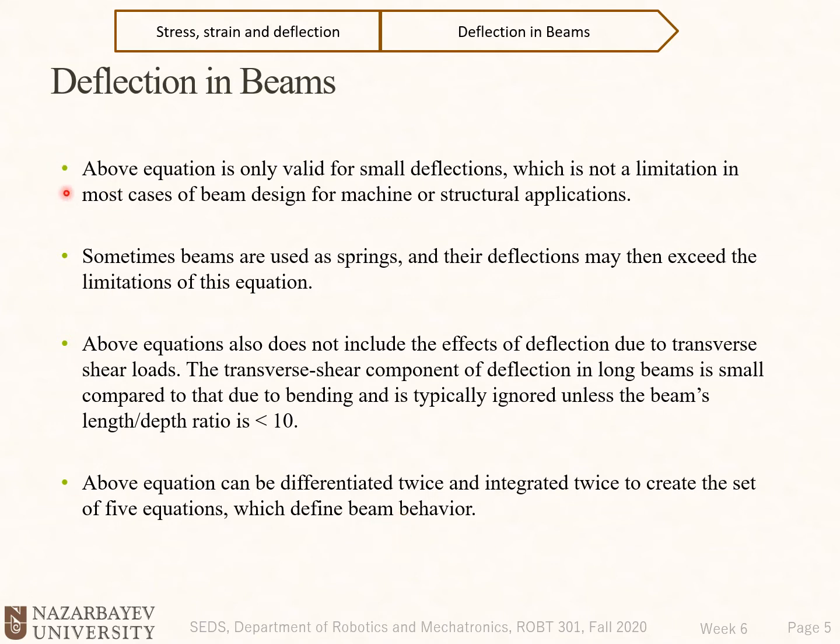So first, this equation is only valid for small deflection. If we are designing a spring and expecting too much deflection, then we cannot use that equation. Plus, that equation does not include the effect of deflection due to the transverse shear load. And we could integrate or differentiate that equation to find a set of equations.